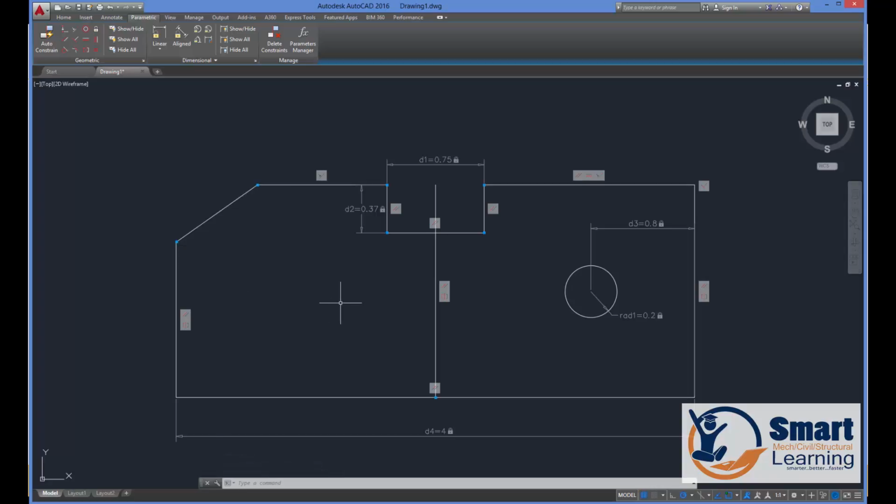So like that you have to find the way which is the best to configure and balance geometric constraints and dimensional constraints. These are two different protocols, geometric and dimensional. So you have to balance both to completely and fully constrain the object.